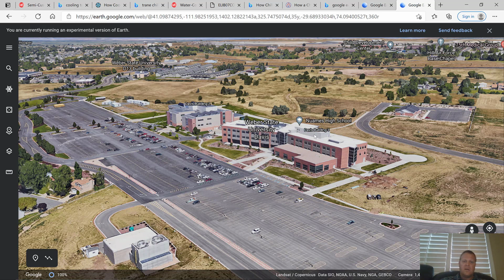I think there's more than one, and it's moving the chill water through this pipe all the way up to this coil. I'm probably oversimplifying it, and forgive me if you're not talking about all the little details of heat exchange, I'm trying to keep it simple. Just imagine this chiller cooling off water and the water coming up and cooling off a coil in one of these air handlers and coming back underground in this tunnel back to the chiller to get cooled off again so that it can go back. So you have this loop here, right?